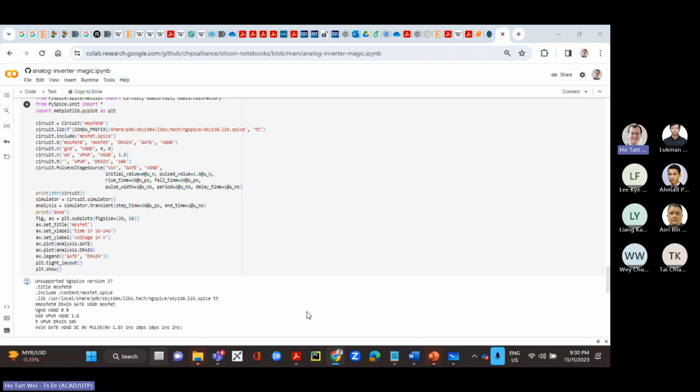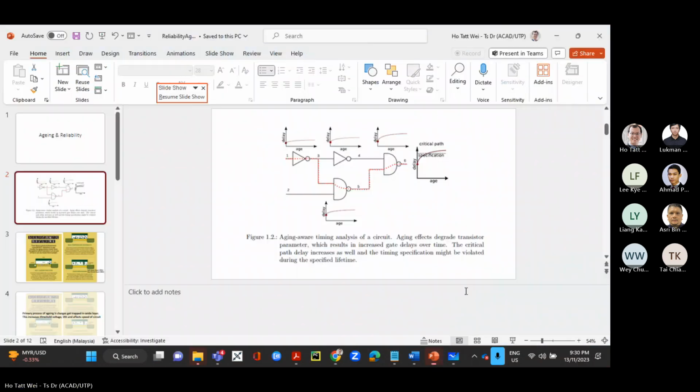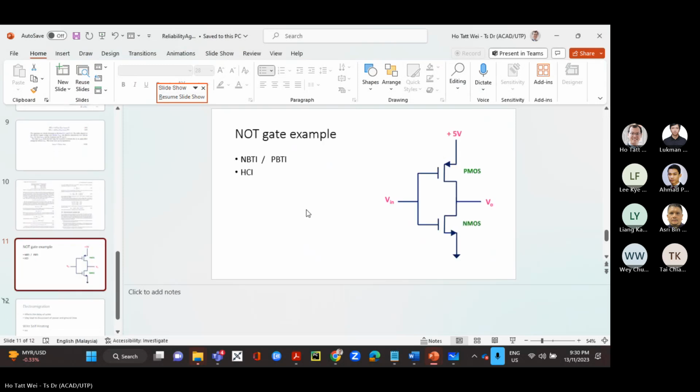So I'm actually asking you to simulate this resistance here. When there's current flowing through here, this MOSFET is acting like a resistor. I'm asking you to simulate it by plotting the IV characteristic of this PMOS, and by plotting the IV characteristic of the NMOS.